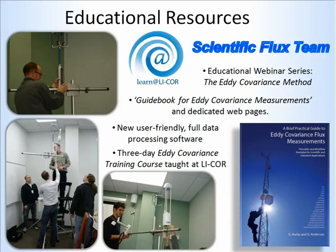But there's certainly other corrections such as the unit conversions, despiking, detrending, time delays, and the frequency response correction actually contains a set of 8 sub-corrections. So those again will be covered in further detail in our in-depth webinar where we step through those. And also these are all explained in good detail with lots of references in the Eddy Covariance handbook.